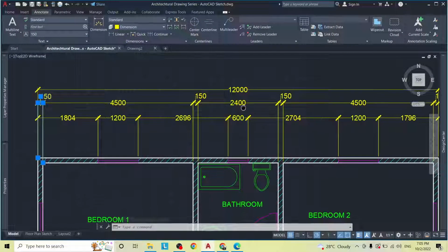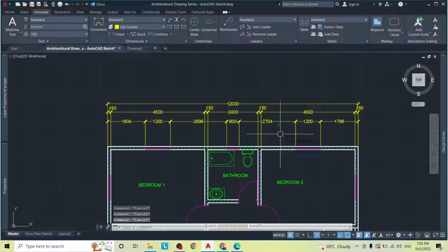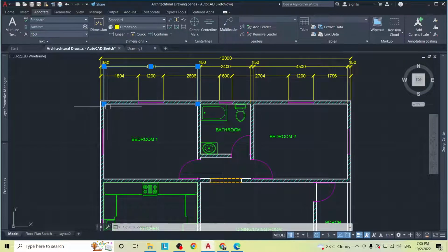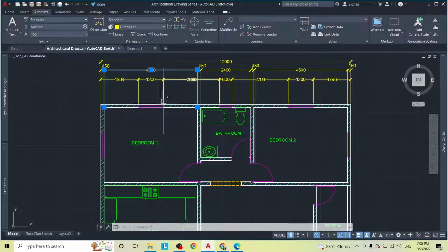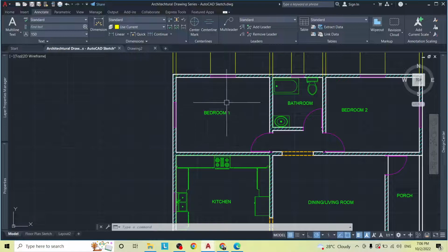Whatever you do, try to be consistent and make sure your drawing looks clean. So that's how we dimension that side. Some people do not put this second row of dimensions, and they put the measurement on the inside of the room to show the width of the room. But then you would still leave the person building your house to wonder what type of blocks you are using for the inside and outside, and it could become tricky if you start using different blocks for external and internal walls, stuff like that.